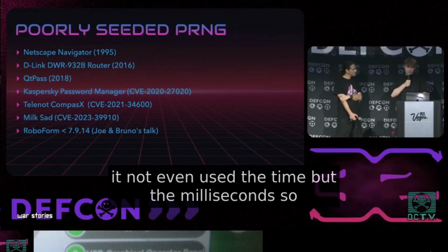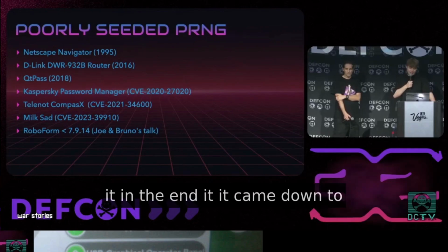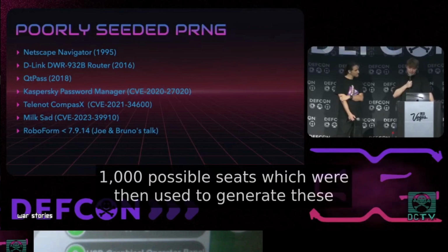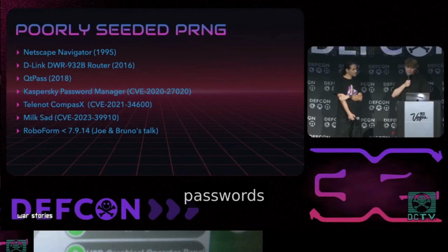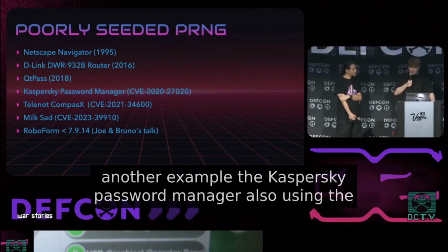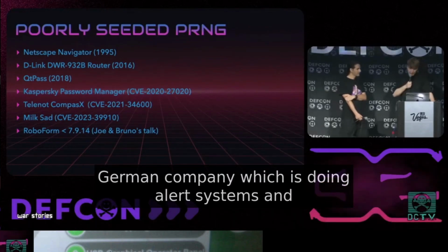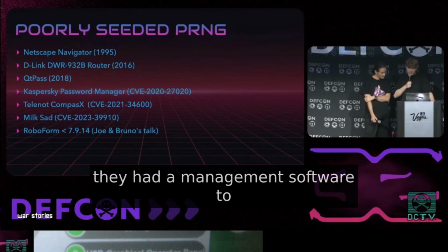The biggest challenge of this whole system is that you must get essentially to the edge of the diode. You don't want to get the light in the center, you want to get to the edge, because you essentially want your reflection to go on and off that diode. If you're in the center, then you're not going to get much variation. But if you're at the edge, that's where you get all the variation. I noticed there was a hair in their photo. Fortunately, there was no hair in the photodiode they sent me, so I didn't have to send it back.